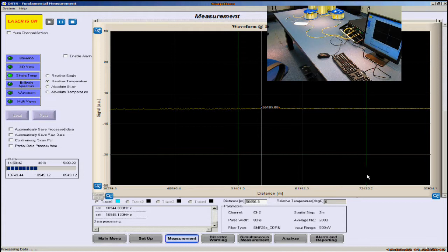So, only a relatively small change in the length from 120 kilometers to 100 kilometers allowed us to tighten the pulse width from 200 nanoseconds to 80 nanoseconds in order to generate a good signal that the Brillouin sensor can measure. So this shows just how the relationships are between fiber length and sensing resolution.